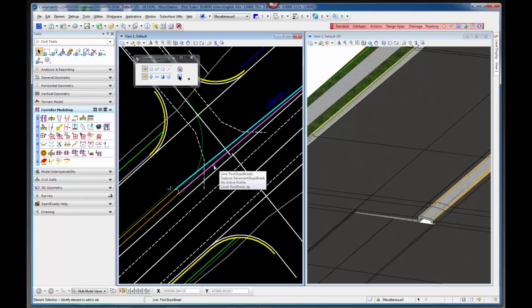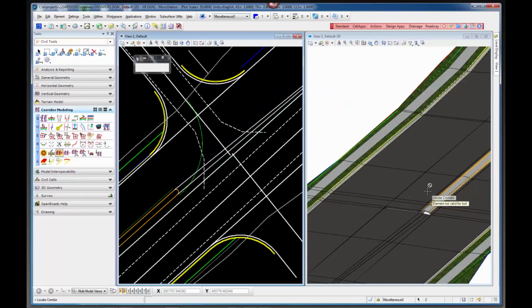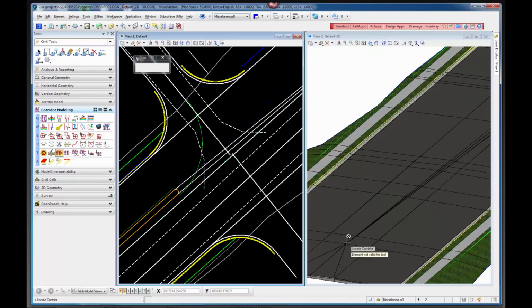So I'll select this line, and I'll go to Add Corridor References, and I'll locate the corridor, and it says data point to apply to references. And now you'll see that the crossover has been added in there, and this pavement actually slopes up to that location, and it will eventually come back to a crowned location back here.